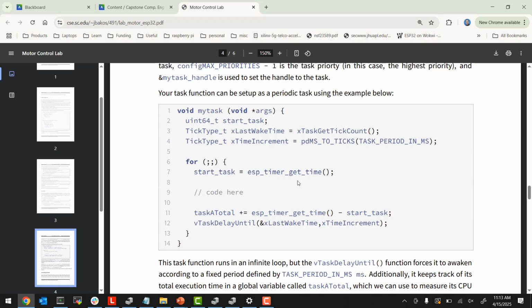It's not dependent on when the task is, for example, if you were doing this manually, you would run the task and then calculate the next time the task should run. But when you calculate that, you're calculating it relative to when that task started. What happens if the task was delayed? Then there's no way to account for that, and you end up getting jitter in the period.